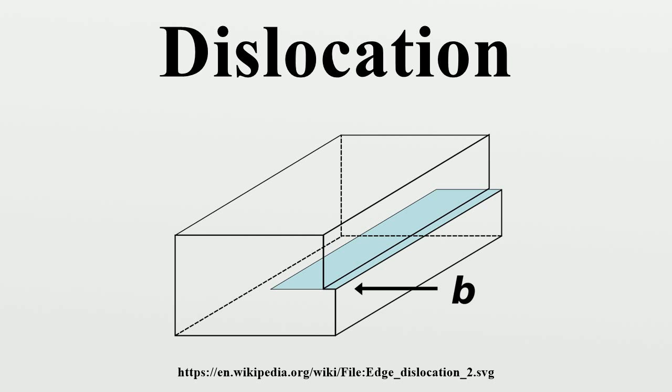Dislocations are found where the line direction and Burgers vector are neither perpendicular nor parallel, and these dislocations are called mixed dislocations, consisting of both screw and edge character. Partial dislocations. Dislocations can decompose into partial dislocations in order to facilitate movement through a crystal lattice.